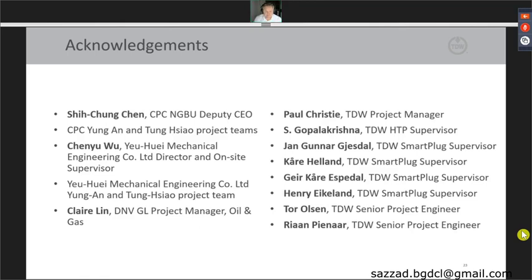Yeah, the communication system that was shown in the presentation was onshore, where there was a unit which sat on top of the pipeline, and then it was wire connected back to a laptop. That is no different for subsea. We would use a subsea skid unit which goes down onto the pipe itself. The depth will be pressure related of the unit itself. So we have tested systems down to about 2,200 meters. So we know we can go down to those sorts of depths.